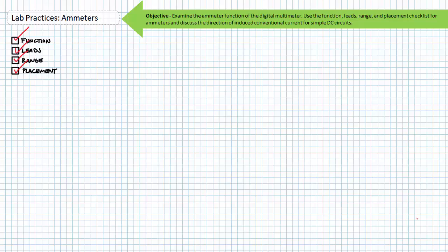In the event you inherit a rotating workstation in the lab environment used by numerous students, always check to make sure that the ammeter input fuse is in place and the fuse itself isn't damaged. Lab equipment gets hammered by generation after generation of students just learning how to use this stuff, and equipment will sometimes just die of despair and exhaustion.